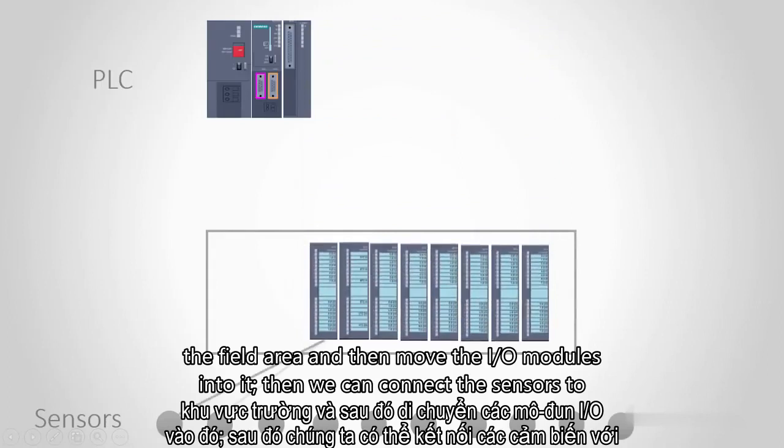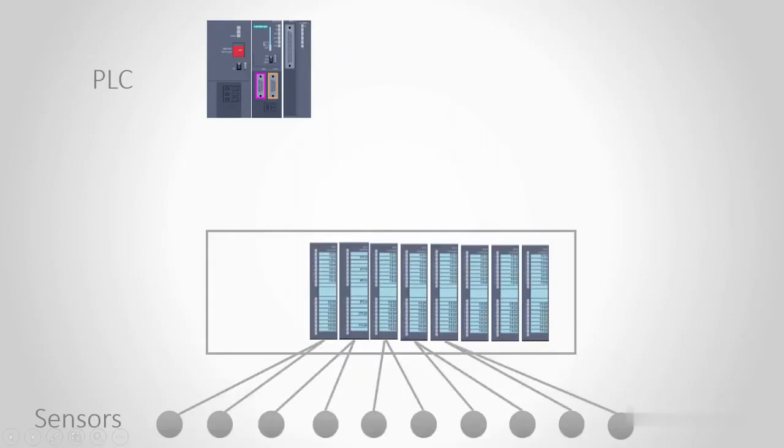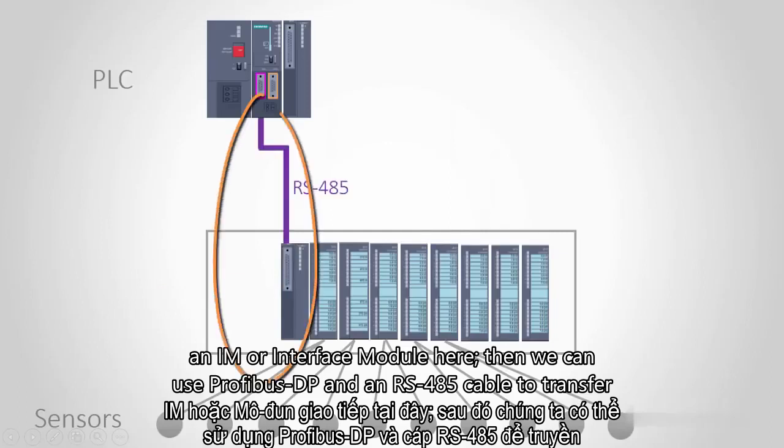Then we can connect the sensors to the I/O modules. Now, to enable data transfer between the PLC in the control room and the I/O modules in the new enclosure, we're going to install an IM, or interface module, here. Then we can use Profibus DP and an RS-485 cable to transfer all data.